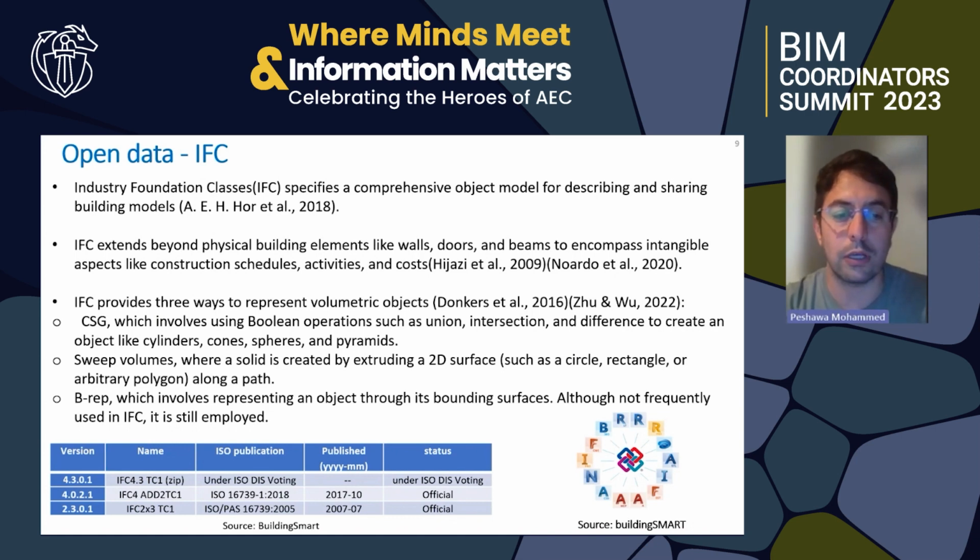So as of August 2023, we have 3 official versions of IFC standard. The first one is 2x3. It is ISO certified, and it was published back in 2007. Then we have IFC 4.0. It is also ISO certified, and it was published in 2017. There are some differences between these two versions. However, one of the most important difference is IFC 4.0 now supports associating geospatial data with IFC.